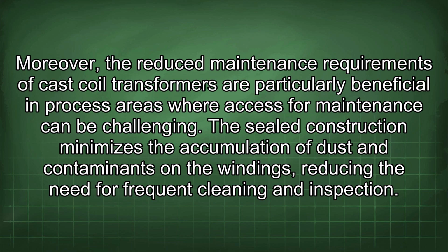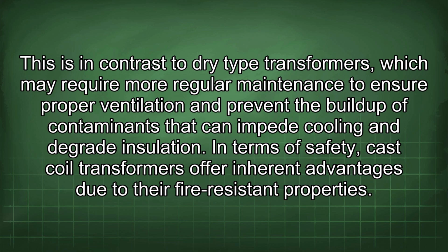The sealed construction minimizes the accumulation of dust and contaminants on the windings, reducing the need for frequent cleaning and inspection. This is in contrast to dry-type transformers, which may require more regular maintenance to ensure proper ventilation and prevent the buildup of contaminants that can impede cooling and degrade insulation.